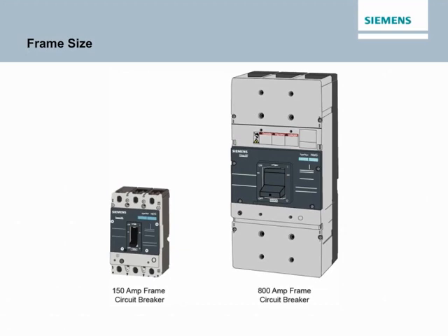The circuit breaker frame includes all the various components that make up a circuit breaker except for the trip unit. For any given frame, circuit breakers with a range of current ratings can be manufactured by installing a different trip unit for each rating. The breaker frame size is the highest continuous current rating offered for a breaker with a given frame.